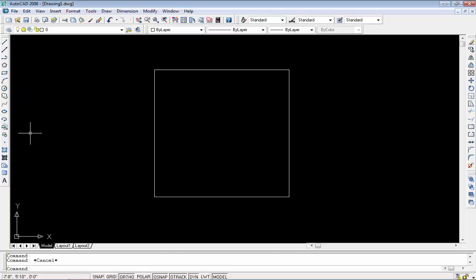So we can't extrude this object, this drawing, this shape in 3D. That means we need a tool which can help us join all these lines so they become one group, one object. So let's look at the region tool. We will use the region tool for this purpose. The region tool's short command is R. Mostly people use the shortcut of this tool, so you should use the shortcut, but I will use this icon. Simply click on this icon.